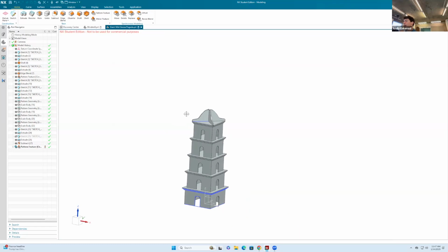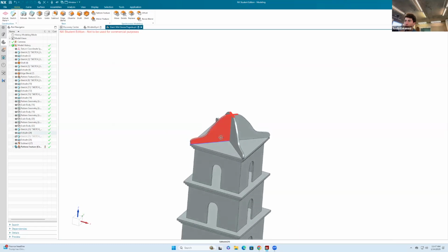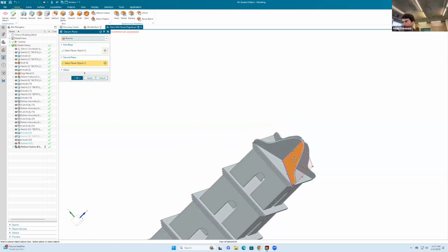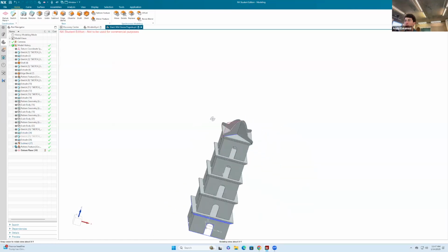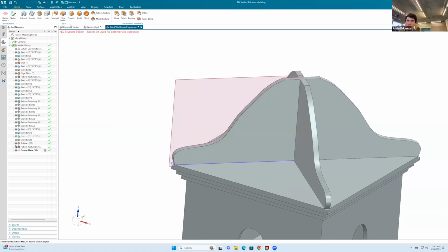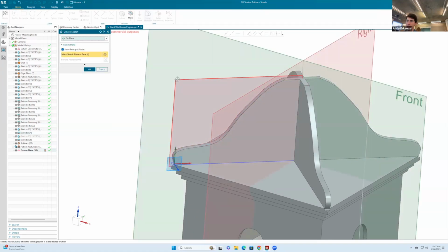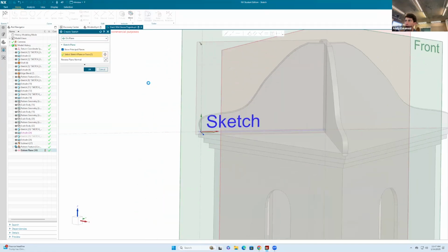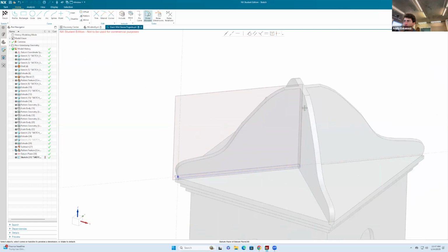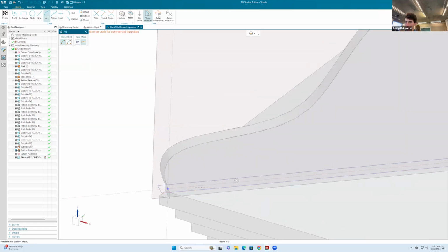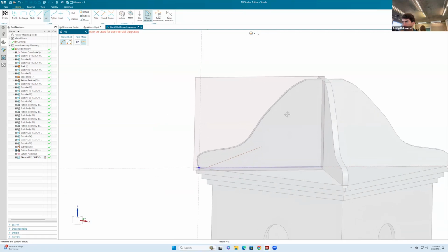That one I actually don't need. Anyways, this is just a little bit of a complicated way of doing this, but it's okay because then I go here to plane, and now I'll create a bisector plane between these two right there. And all that we're left to do is just create a sketch in here. I'll say, okay. And I just want to now draw an arch that is gonna go, say, from this point to that point.